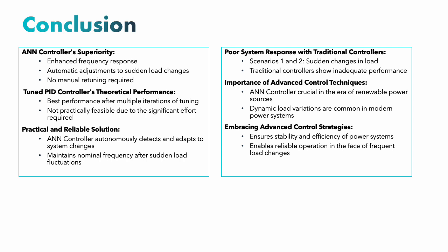In terms of the tuned PID controller, yes, we got better performance after several iterations, but practically using the tuned PID controller won't be feasible, because when there's a sudden change, we would have to go back and retune the PID controller, which is okay theoretically, but practically it's not okay, looking at how dynamic our power system is nowadays.